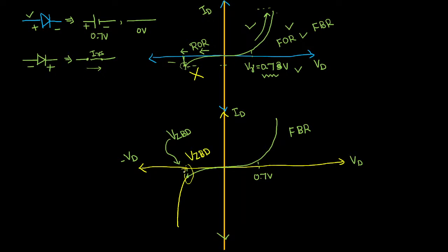Nice, sir. Basically, what will happen here then? I have highlighted that if you take a normal PN junction diode in forward bias, it will be represented like this. Either it will be short circuited or 0.7. Short circuited means the ideal case. 0.7 means the practical case. Whereas in the reverse bias, it will always be open circuited. You have to replace the diode by its equivalent open circuit.